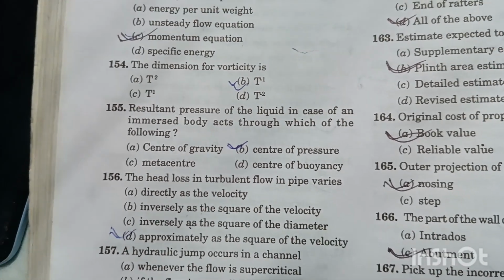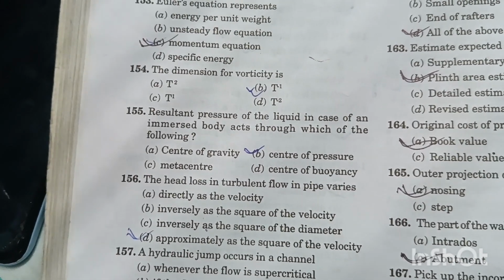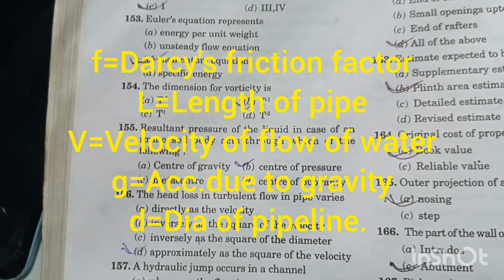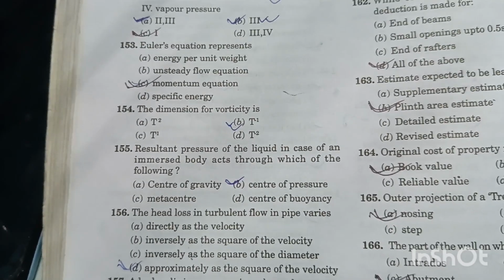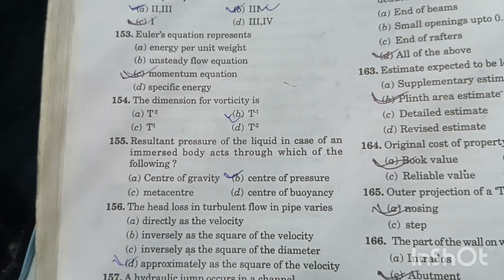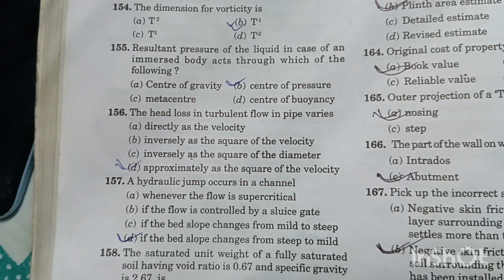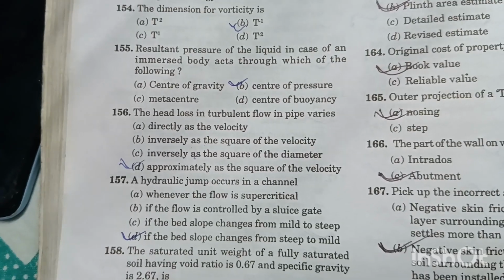Head loss in turbulent flow in pipe is equal to 4fLV² divided by 2gD, where D is the diameter of the pipe, g is the acceleration due to gravity, f is the Darcy's friction factor, L is the length of the pipe, and V is the velocity of water. Question number 157. A hydraulic jump occurs in a channel if the bed slope changes from steep to mild and subcritical flow to supercritical flow. Option D is the right answer.